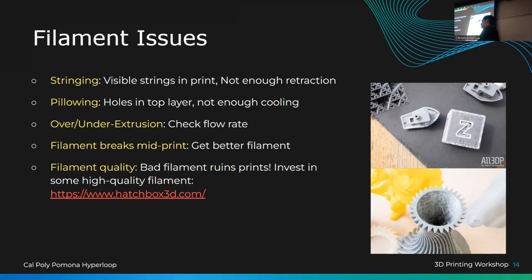That's why some people opt for what's called Bowden, right? And Bowden is the system that you guys are going to be using today, where basically the motor sits on the outside of the tool head. You can run them faster, hopefully, right? And the problem is that you'll have to be a little bit less forgiving with how quickly you need to retract and unretract and everything like that. So yeah, it just depends. Big issues. Bad plastic can also be a problem for that too.